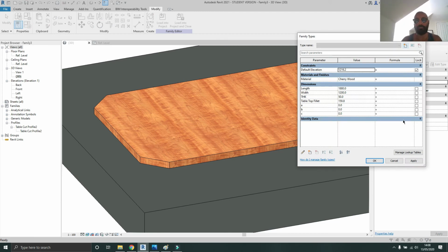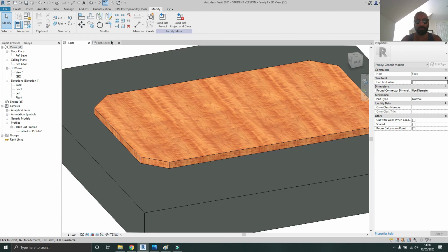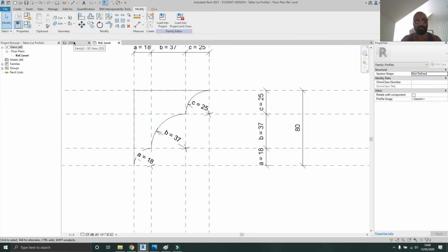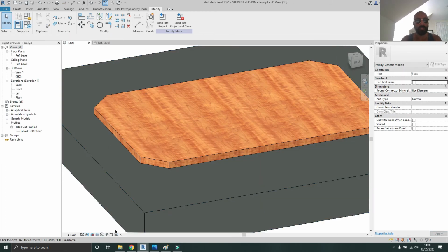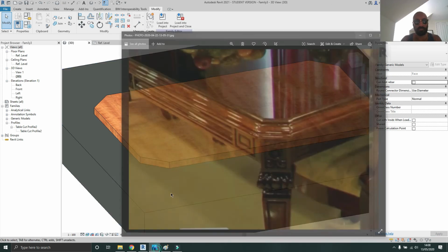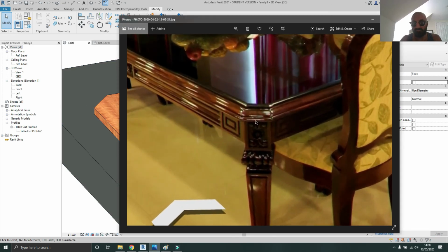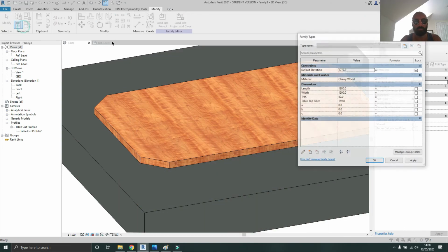So we want A, which is the bottom one, I believe. Yep, bottom one. It goes from bottom to top. A was going to be 0.25 thick, sorry, 0.25 times THK. These are case sensitive, by the way, so remember that.